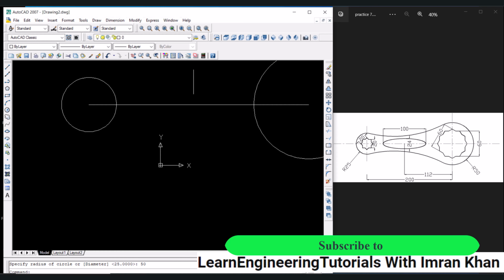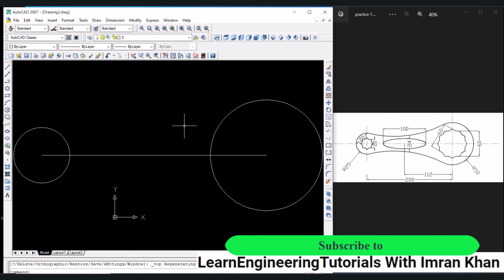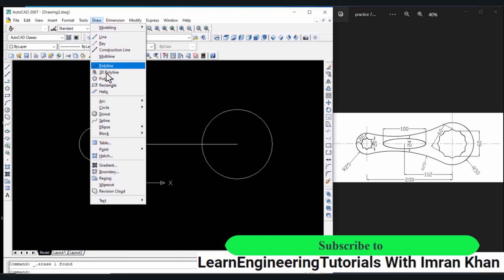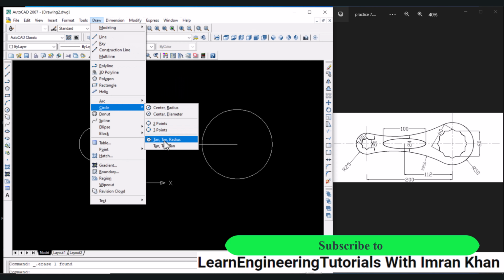Now if you can't zoom out, click on top view, and now you will be able to zoom out or zoom in. Here we can see an arc. The radius of this arc is given as 250, and the other information is that this arc is touching this circle, so that means it will be tangent to this circle and over here as well. So we will utilize the tangent radius option inside the circle.